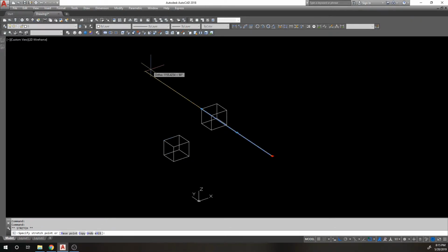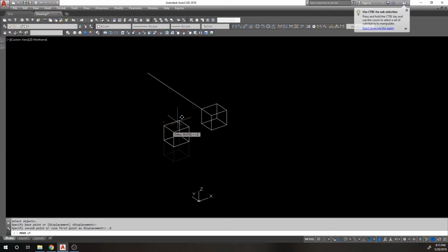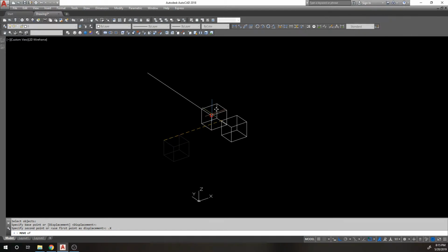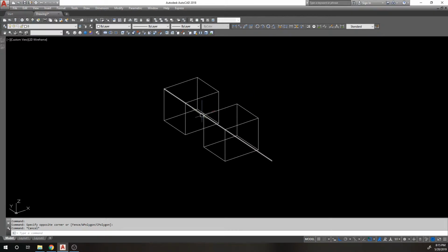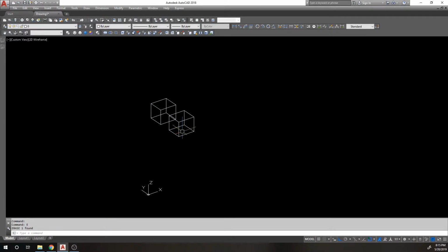So I'm going to put this way, okay? And I'm going to move this dot X, match it up with this corner here, or this line, doesn't matter. Click @ symbol. And now, dragging this line through, you can see that it matches up perfectly. Because what I've done is I've moved this corner of this object to match the corner of this object at that same coordinate. I've locked in that coordinate for the X-axis. That's what you're doing, just in 3 different axes, okay?